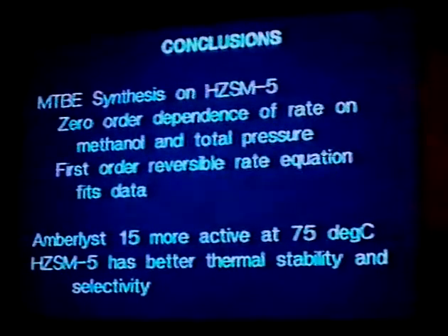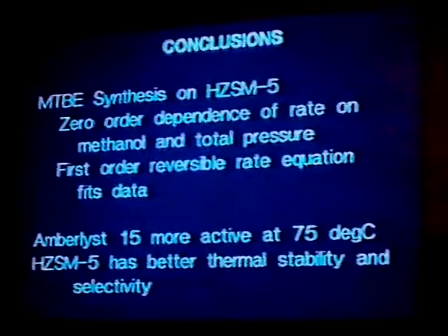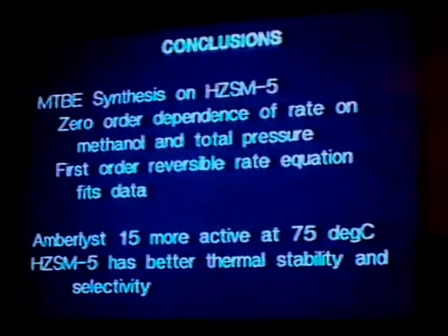Our conclusions on this work are that, again, we saw a zero-order dependence of the rate on the methanol concentration and on the total pressure. We found that the first-order reversible reaction rate equation fit our data, and that the Amberlyst 15 catalyst was more active than the zeolite catalyst at 75 degrees C, but of course it lost its activity at temperatures above 90, and that the zeolite catalyst had better thermal stability and selectivity than the Amberlyst 15.